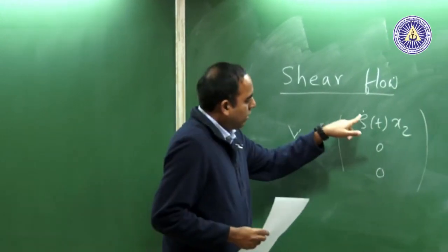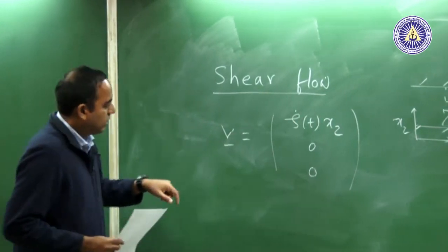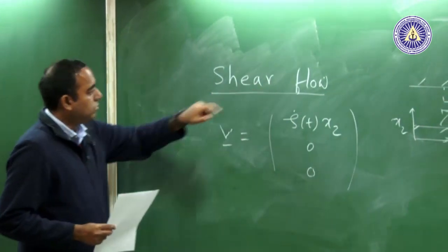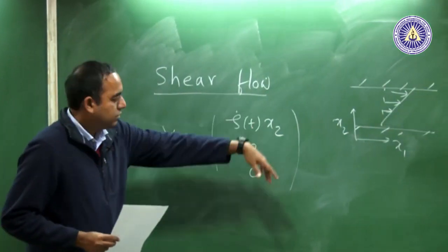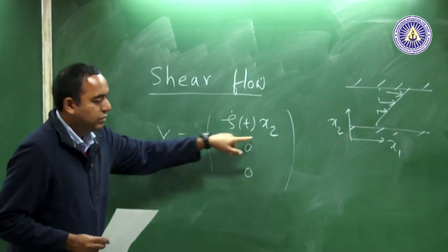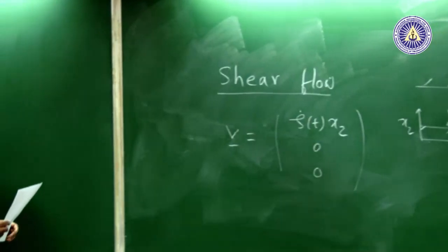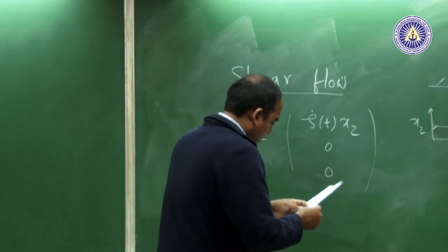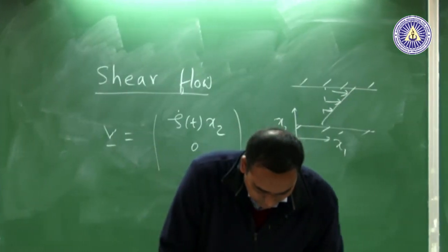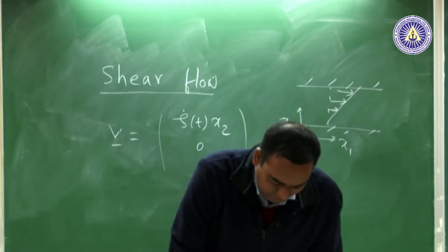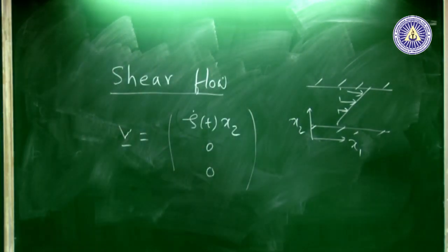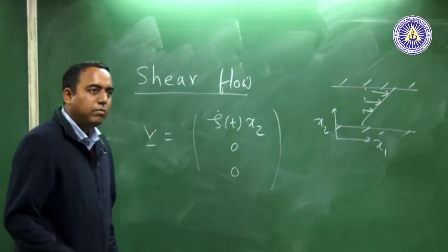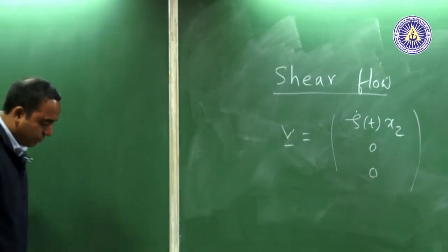Now, notice that the shear rate here can be a function of time. So, even though we are talking about simple shear flow, this standard flow would have several variants based on what time function we impose on this shear, and we will come across all those variants one by one. So, this is the first type of standard flow that we use for characterizing non-Newtonian fluids, and what turns out is that a simple shear flow or any kind of shear flow is really a mild type of flow. So, mild and strong are relative terms to use.